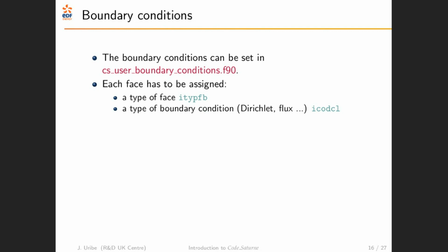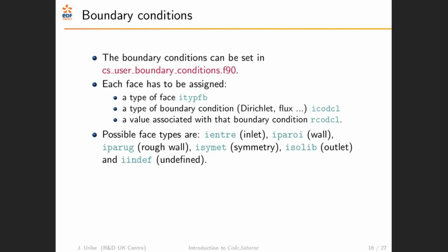And so for each face, you need to define a type, which will be this ITYPFB, the type of boundary condition, and the value of that boundary condition. Okay, so the possible types are inlet, wall, rough wall, symmetry, outlet, or undefined.